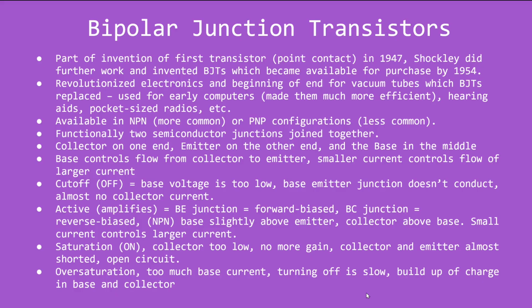Oversaturation is going to be too much base current, and turning it off again can be relatively slow because you get a buildup of charge in the base and the collector. I can't think of any applications where oversaturation is actually a good thing.